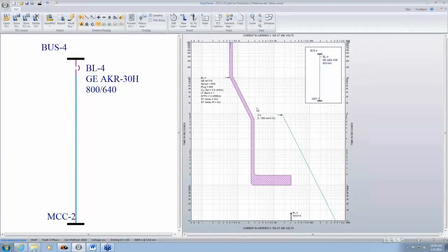It's a lot of gap. Now we would have problems if this curve was on the right side. If the protective device, or the circuit breaker curve, was on the right side of the damage curve, that would be a problem. So as long as you're on the left side, you are going to trip before the damage point for the cable is reached.